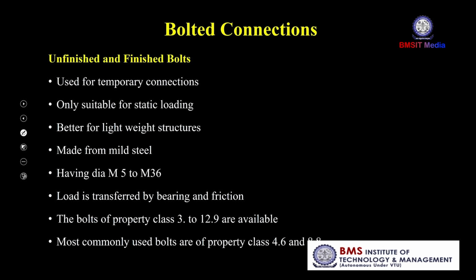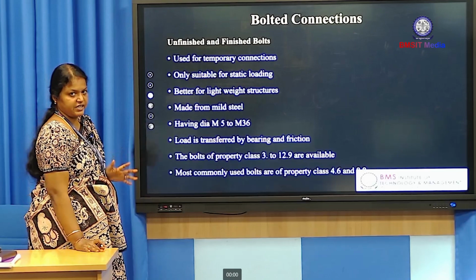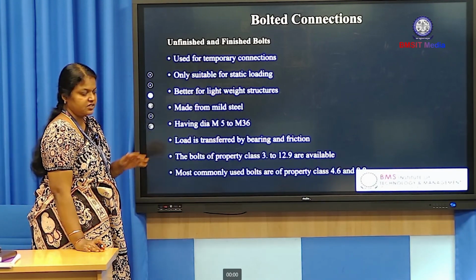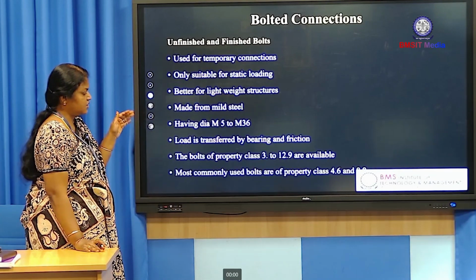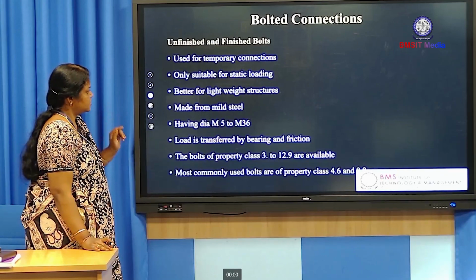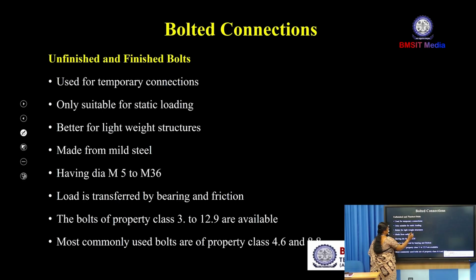Now coming to the unfinished bolt. This is used only for temporary connection. This is not a permanent connection. Welded connection is the permanent connection, and bolted connection is temporary; if we want, we can remove the bolted connection. Next, it is only suitable for static loading. It is not suitable for dynamic loading.